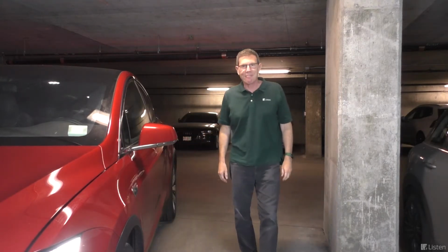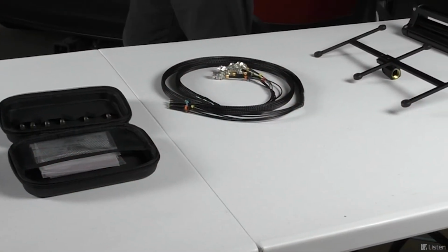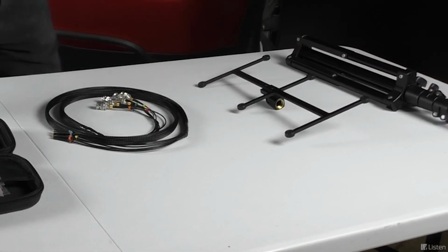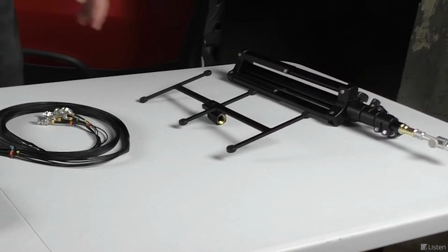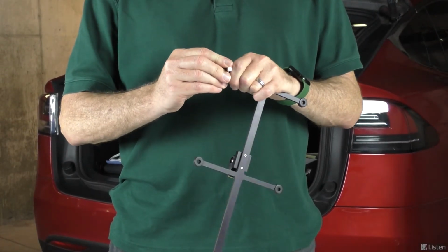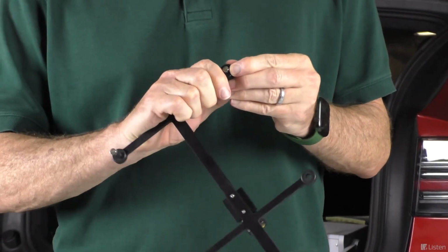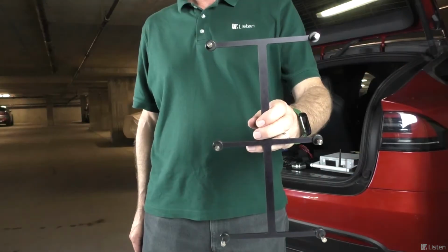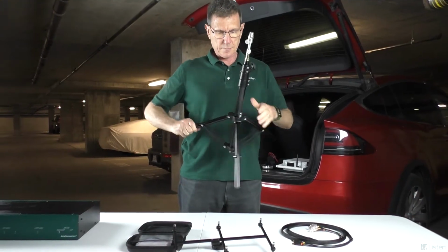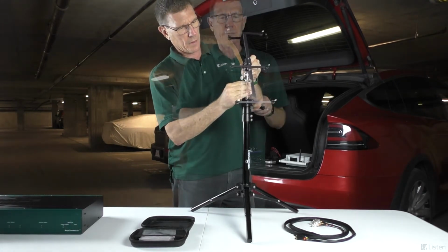All right, let's make some measurements. We use a 6-microphone array to represent the driver's head in the driver's seat. This is pretty standard for automotive audio test. Let's get this set up. First, I'm going to put the mics into the array. I'm using our own SEM measurement mics, the short version, because they are nice and compact, but you could use any 1/4-inch measurement microphone. Now I'm going to attach this array to the tripod so that we can adjust the height to the position where the driver's head would be.